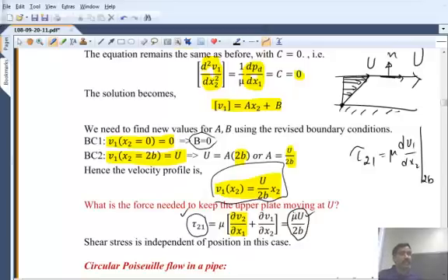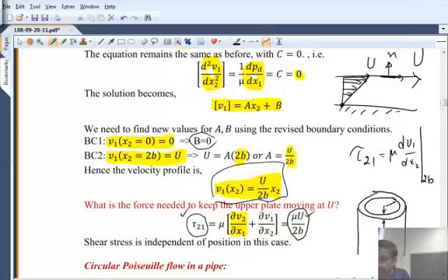Now the question is, how can I devise this infinitely long plate? And the answer is you cannot. But a clever variation on this would be if I take two concentric cylinders that are very close to each other, with a small gap. What would be the velocity profile in that gap? Imagine that the gap is much smaller than the radius of the inner cylinder. If I cut the cylinder and stretch it out, what do I have? Two parallel sheets, right?